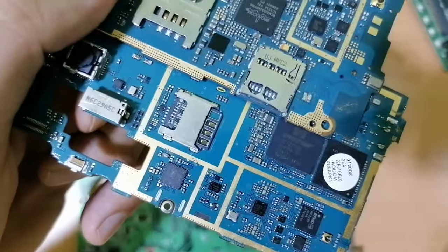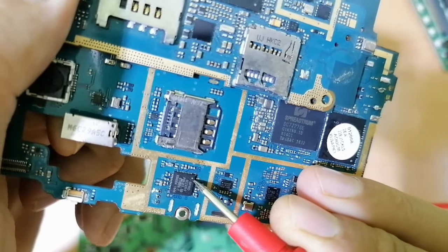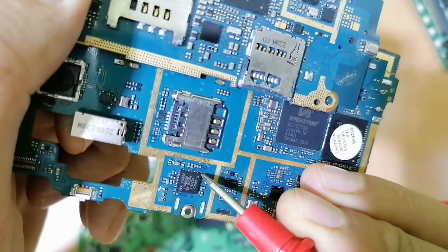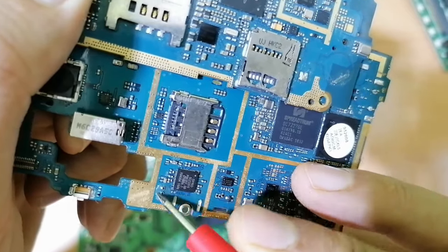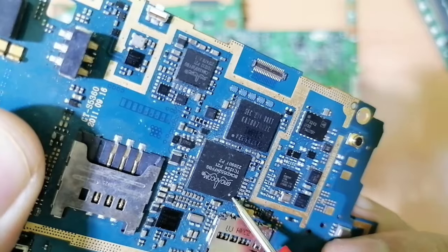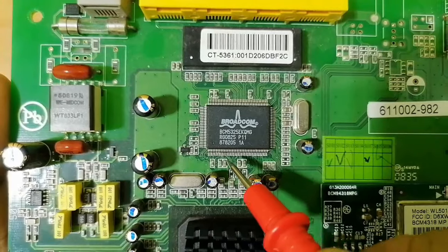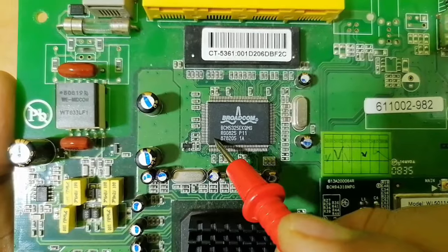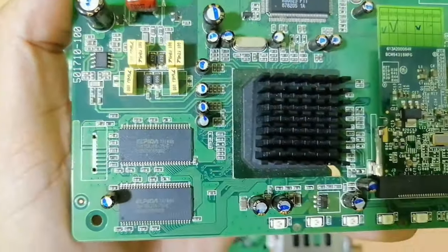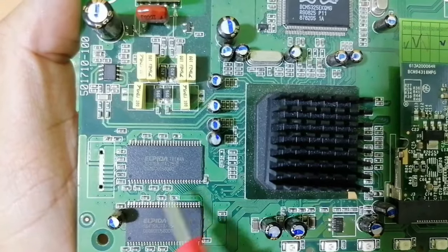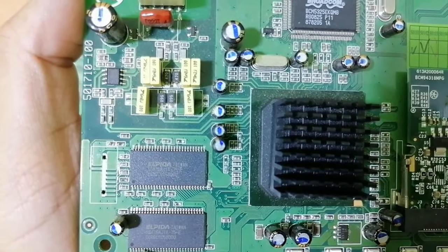Let's see, for example, this IC. As you can see, we have the dot over here. You see this dot means this is pin number 1. And as I told you, we always have some capacitors around the IC. Here also we have the dot over here, meaning pin number 1. Also we have a dot over here. Do you see? This dot means this is pin number 1. And if we go here to this chip, this is basically the RAM. We have a dot over here and a dot over here, meaning this is pin number 1.